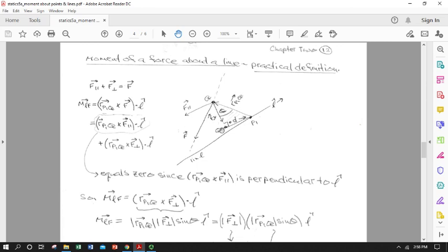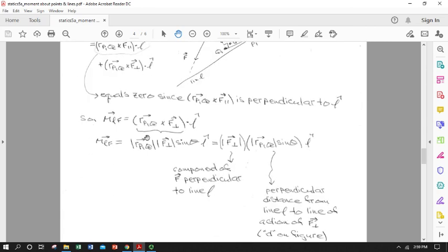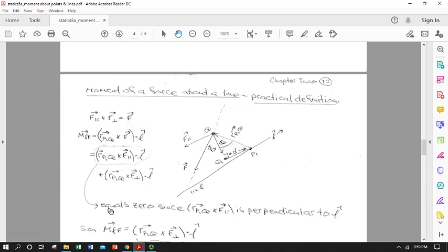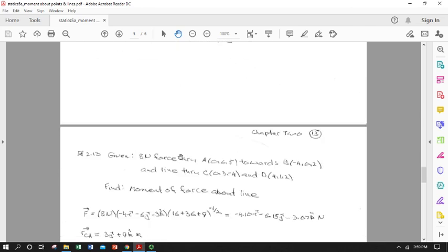So I can do all of this geometrically, or I can use my cross product and dot it and get the portion of the moment that's parallel to the line, the turning portion, and then just subtract it from the total force vector to get the remainder. I won't step through all of this, but this is another way of looking at which portions of a force are going to turn something versus make the shaft slide axially along its length. So basically a whole lot of different ways of saying the same thing.